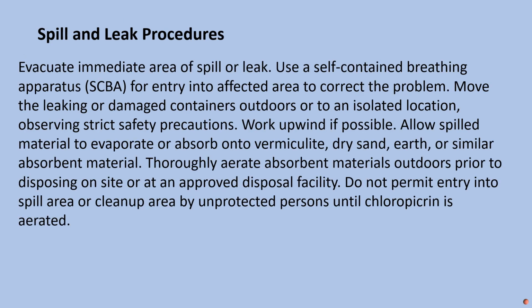Spill and leak procedures. Evacuate immediate area of spill or leak. Use a self-contained breathing apparatus, SCBA, for entry into affected area to correct the problem. Move the leaking or damaged containers outdoors or to an isolated location, observing strict safety precautions.